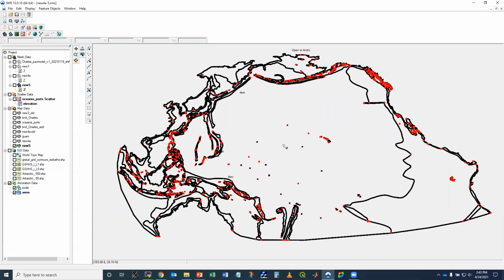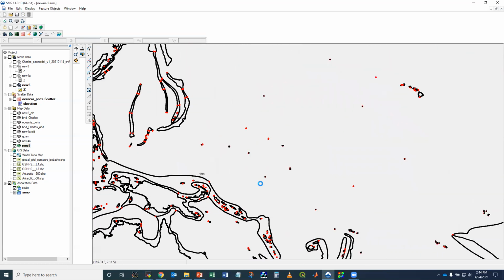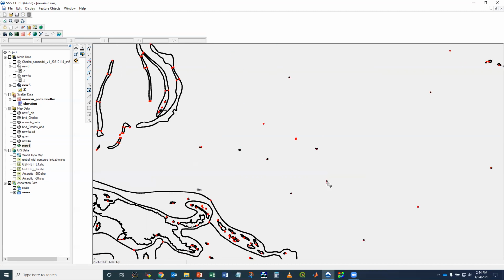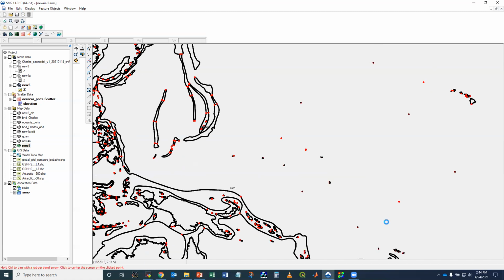Regimes. So another thing you notice is that in most of the islands, we do not use auxiliary arcs, right? We allow the mesh to organically transition the resolution smoothly inside the island regimes. So if you zoom in on any of those islands, you don't see any auxiliary arcs because most of the islands at the moment are resolved with a 1 to 3 kilometers resolution. So that's still okay, even though the bottom slopes can be very steep at places.